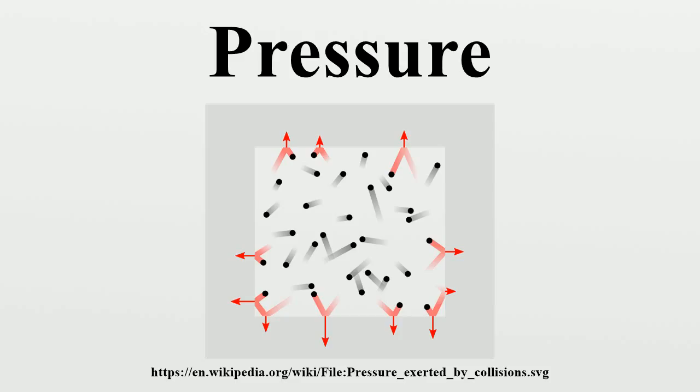It is incorrect to say the pressure is directed in such or such direction. The pressure, as a scalar, has no direction. The force given by the previous relationship to the quantity has a direction, but the pressure does not. If we change the orientation of the surface element, the direction of the normal force changes accordingly, but the pressure remains the same. Pressure is transmitted to solid boundaries or across arbitrary sections of fluid normal to these boundaries or sections at every point. It is a fundamental parameter in thermodynamics, and it is conjugate to volume.